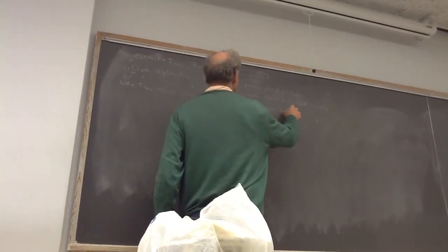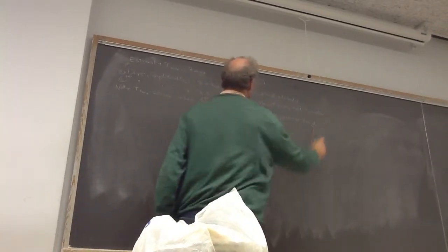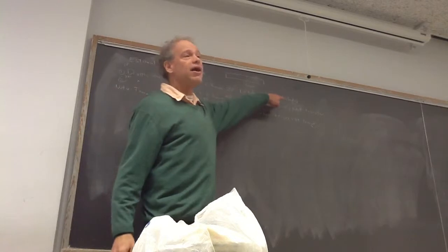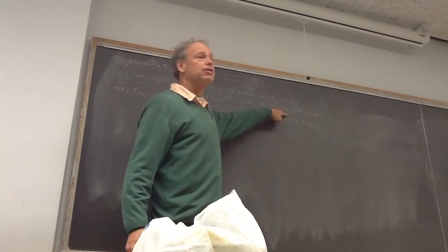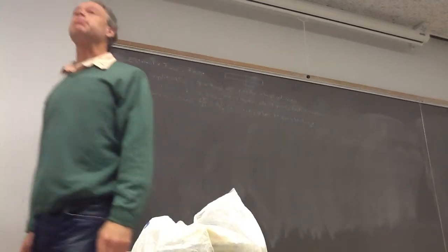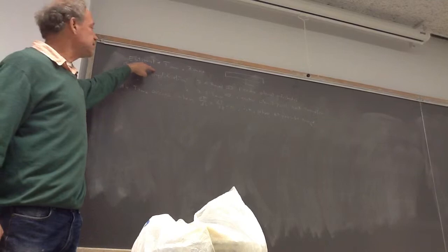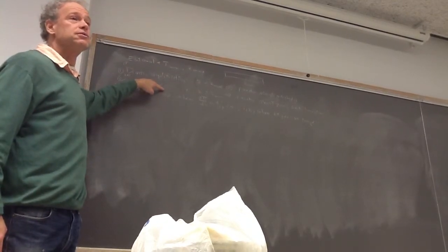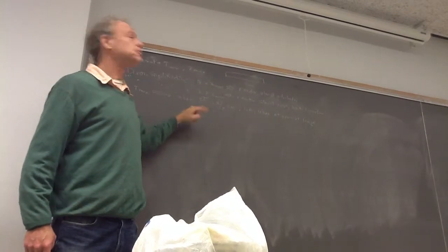When heat generation equals heat transfer. Well, here I have heat generation because it's adiabatic. Here I have heat transfer. So what I'm going to do is plot the heat generation due to this, and plot the heat transfer due to this. And where they cross will give me an estimate of Zmax.